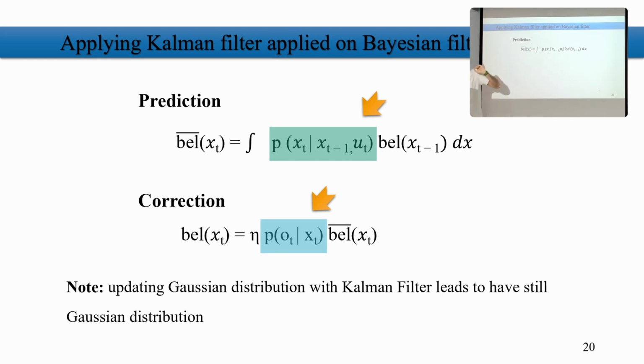Predicted belief means, very important again, that my robot is over here. I'm running, go to 3 meters, for example. Then I know this control command. I want to calculate the predicted belief of where I am, based on the control commands, the previous pose where I was, and the previous belief of where I was. And don't mix these. This is the belief of the Kalman filter calculation, and this is the pose, if we are talking about the X, Y, and orientation or bearing.